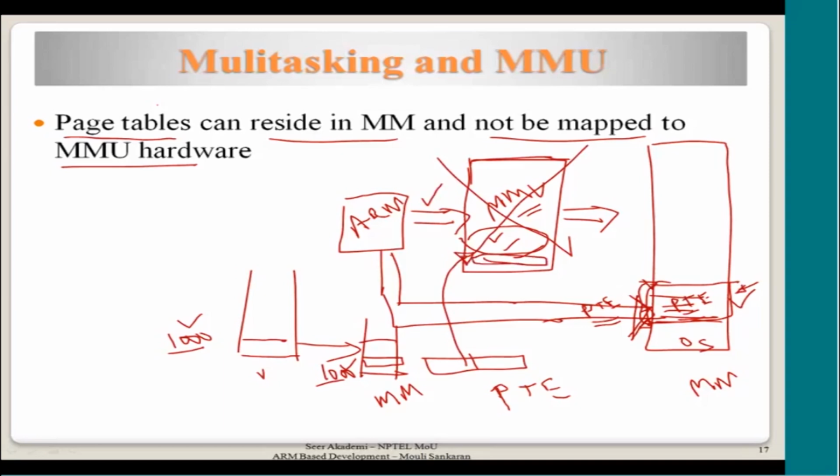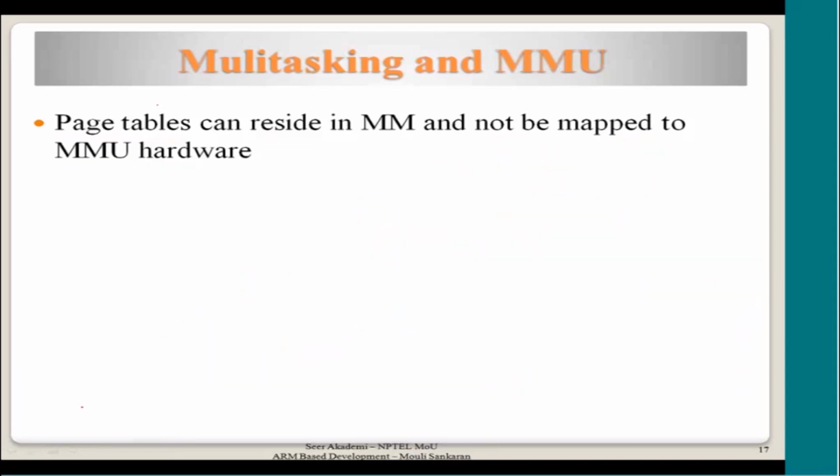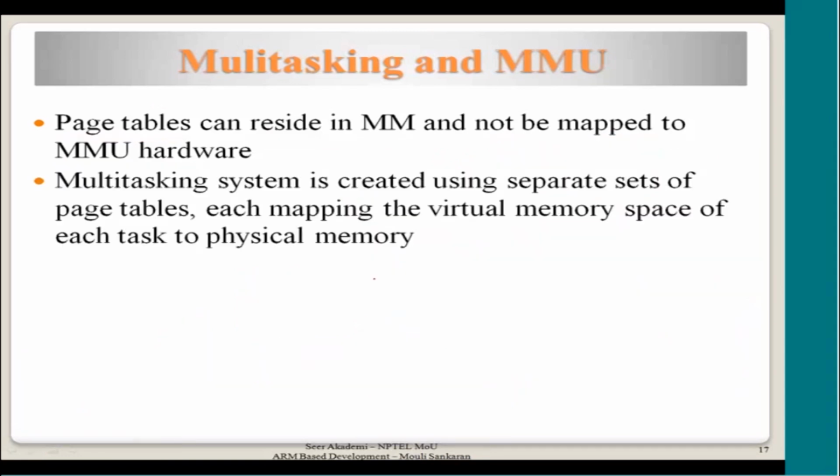So we need this information to configure it, and we cannot use the MMU for doing it. That's why the page tables are always one-to-one mapped. Let's say the addresses are one-to-one, so there is no difference between the virtual address and physical address of the page table. That's what I'm saying, it is the same. So then we can short circuit the MMU, right? We don't need the MMU. As soon as these addresses are generated, it will not even enable the MMU. It will go onto the address bus directly without any translation. That is also a job of the decoders in the system.